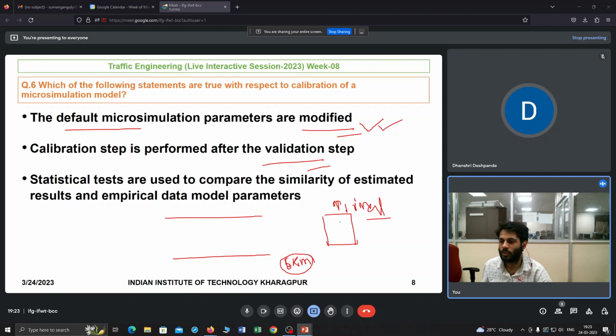So these are some parameters 1 2 3 4 5. So now it is necessary to do a validation. Suppose for a particular traffic condition during peak hour and particular road geometry you have done this calibration, but how to ensure that these calibration parameters are also valid for off-peak scenarios? It may not be valid.